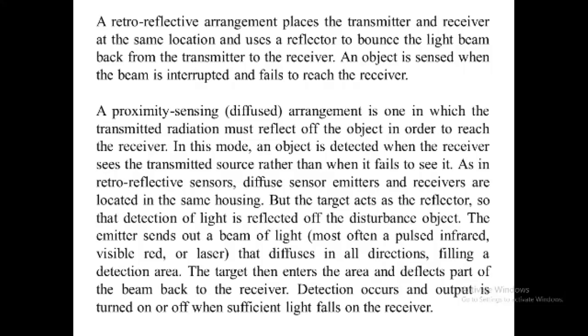A retroreflective sensor can be used to detect large objects, objects moving at high speed, reflective tapes at high speed, and to sense transparent or clear glass or plastic products.